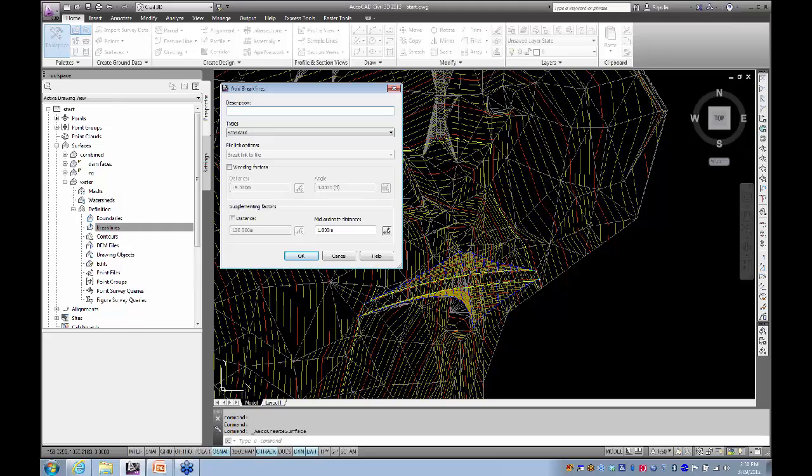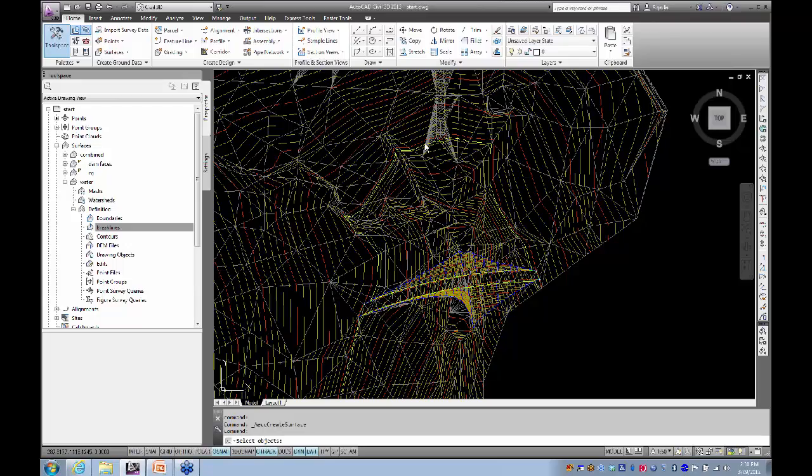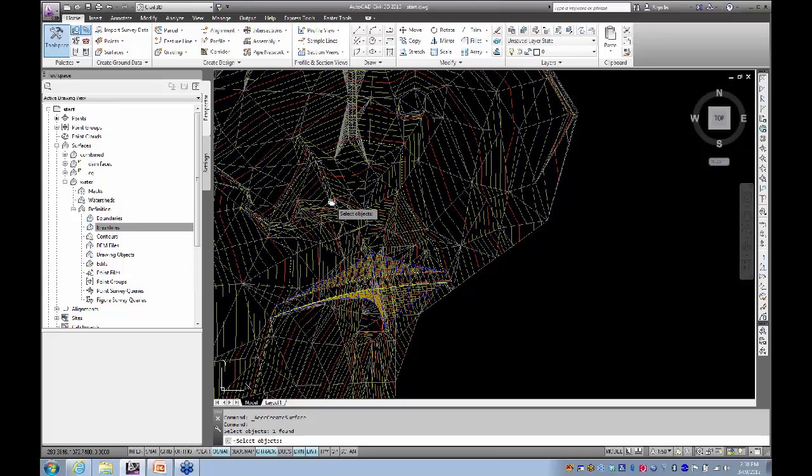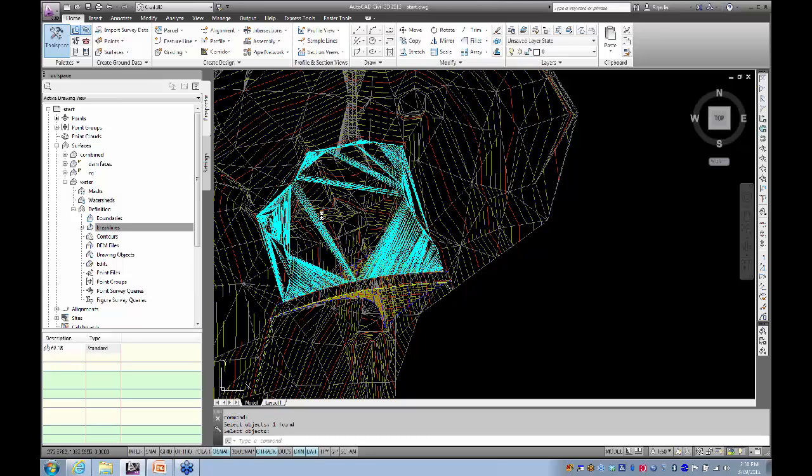And we can call it, yeah, break line would be the one. Call it 68.18. Type of standard, which is fine. Middle distance is fine. We don't have any curves, so that should be it. Go OK, and select that as its own water level surface. There we go.